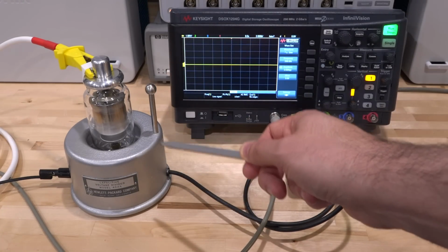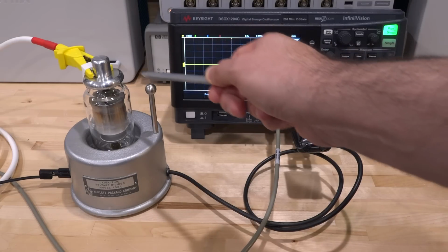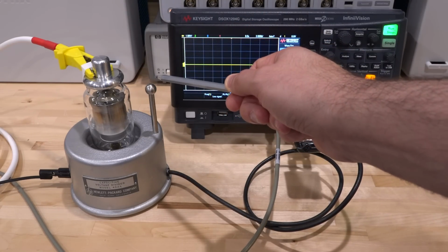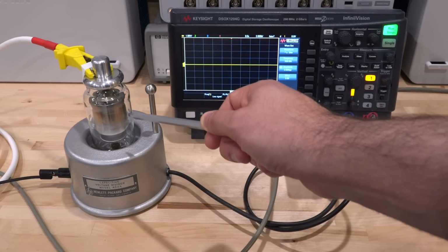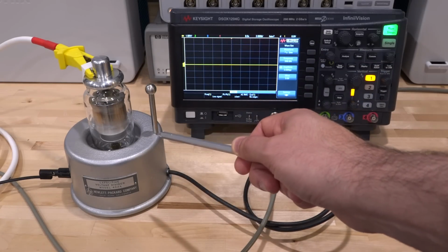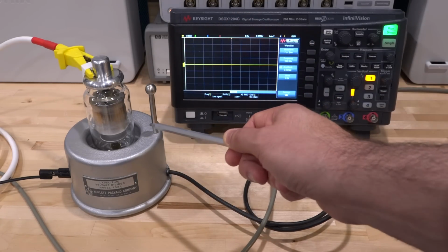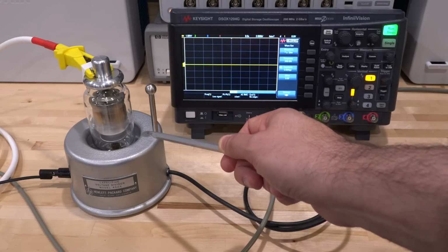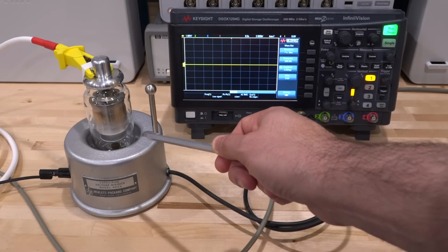But even this has its own limitation because you can see there's an arc gap across here. If you go too high in voltage, you will arc across and it will certainly scare the heck out of you, but it will prevent the tube from breaking down. There's also a current limit because this is a capacitive divider. The amount of reactive current going into it is a function of frequency. So we're going to measure this at lower frequencies, at around 200 hertz, even though you can really use this up to tens of megahertz.